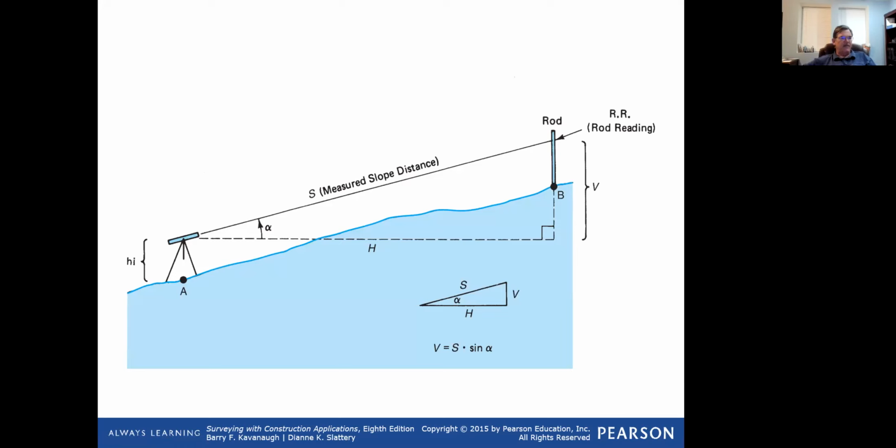I did work like that for a landfill, actually, and it was to see how much would go in the hole. The Appeal landfill in Calvert was set up like that. We did some work that way. Here, people don't normally do this. You can. You want to know that distance. You can get a slope distance. You can read the angle on a slope, get this angle, and figure everything out. People don't usually do this. If you're going to go through that much effort, you're going to use a total station.